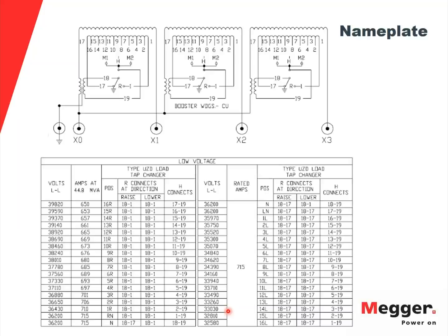In North America, it's very common to have a de-energized tap changer on the high side or primary side and an on-load tap changer on the secondary side. You can run into different designs of on-load tap changer. In the example I have right here, I have a regulating winding that gets connected in series with the main winding, and as you can see, it has 16 tap positions and a reversing switch.